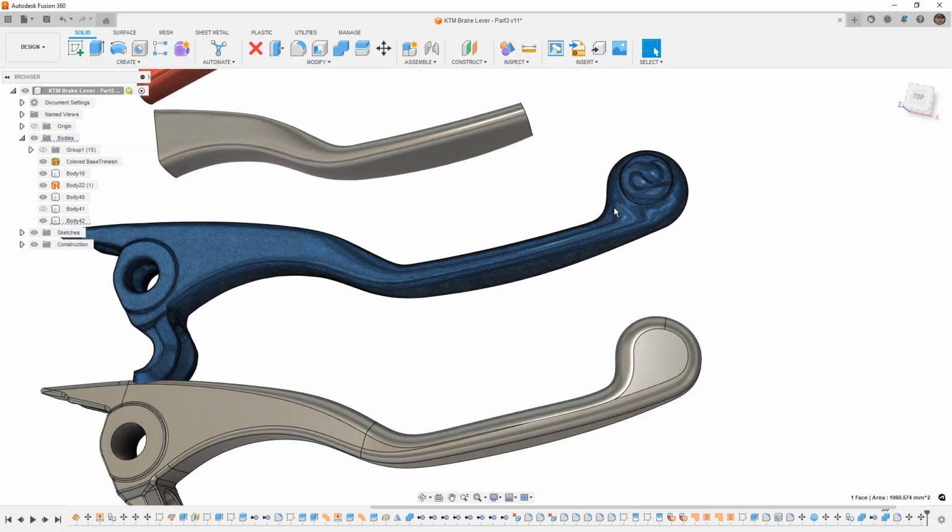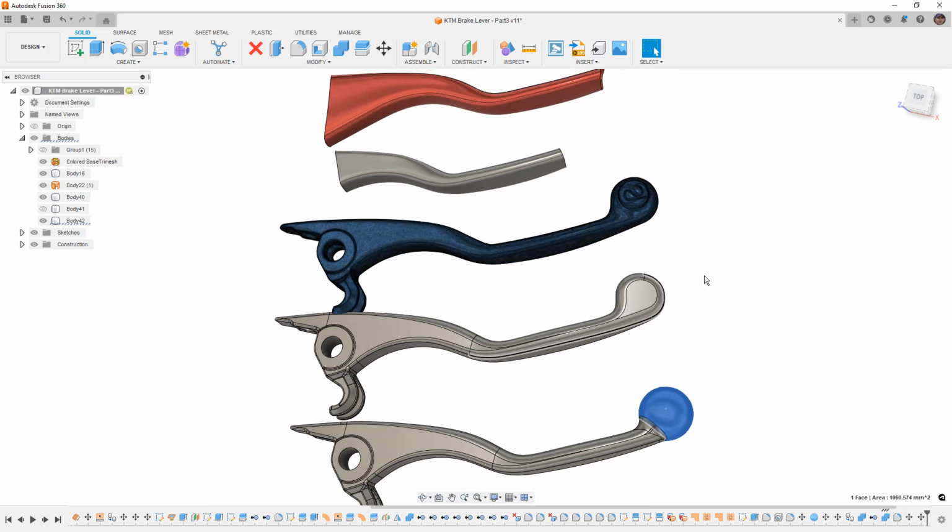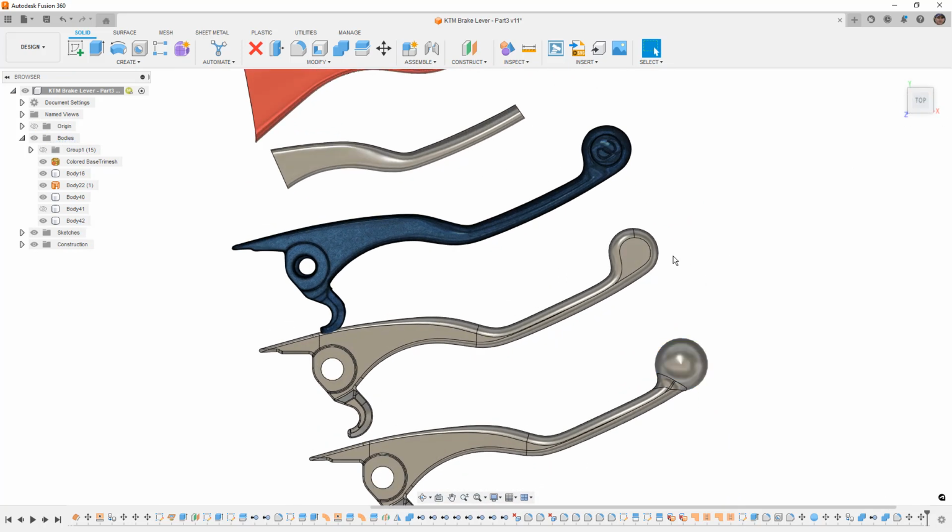So again, these are little nuances that you need to think about. Most of the time when you have a CNC machined version of this, it's probably just like this. Now these balls on the end, they're generally hollow on the bottom and they're made to break off in the event of a crash. So that way you still do have a lever and it doesn't just break or bend all the way up here near the pivot. So that's the main reason for those things, to make sure that they don't impale you if you crash, and the little balls on the end generally break off.